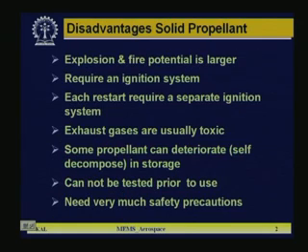On the other hand, there are also disadvantages of solid propellant. What are those? Explosion and fire potential is larger compared to liquid propellant. This is an explosive material in most cases, and is very prone to fire. It requires an ignition system, because since it is an explosive and has to be fired, you need an ignition system. Each restart requires a separate ignition system.